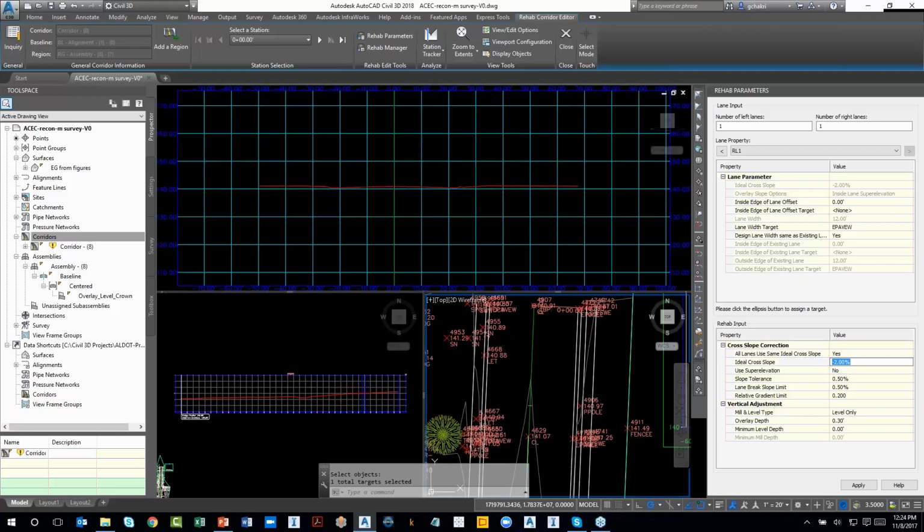You want to say, okay, I want to give a cross slope tolerance of 0.5 value, which is what you specify here, and therefore do an optimization for the cross slope based on that. So in this case, because you have an existing ground at 1.3 and your ideal is 2, the difference is 0.7. So you're going to lift up or compensate your design slope from 2.0 to 1.8. Now the difference between 1.8 and 1.3 is 0.5. You're within the tolerance now.